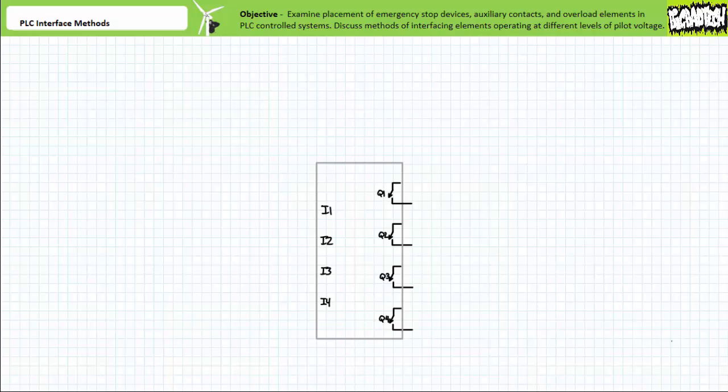Although this separation between pilot and primary signals should be simple in concept, complications to this methodology exist when we introduce a radically different means of control in the form of a programmable logic controller, or PLC. PLCs are industrial computers that, in summary, examine inputs, run a program, and issue outputs. PLCs, barring some peculiarities, closely mimic the behavior of those systems employing hardwired relay-based ladder logic. However, they are flexible, reprogrammable devices that make quick modification of a system possible without the time-consuming necessity of physically rewiring it.